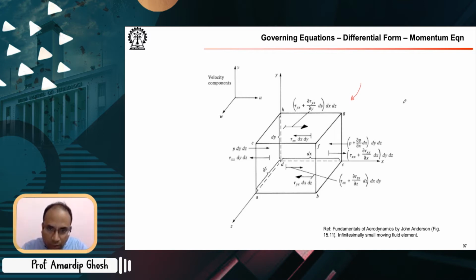So these governing equations in differential form, when we non-dimensionalize them, these non-dimensional groups fall out in front as coefficients, and it can be shown that they act as similarity parameters and create dynamic similarity between problems when the similarity parameters are the same and the geometry is okay. So the flow is over similar geometrical shapes.